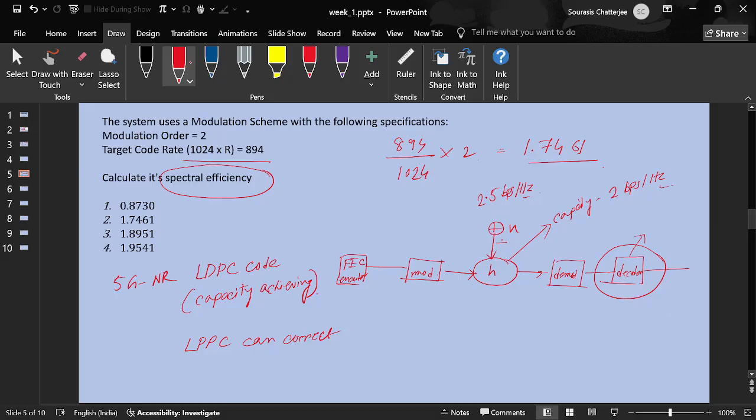I am not supposed to face any issue, right? Because I am using forward error correction, or I will encounter some issue. What do you think? Because if I am using error correction anyway, the decoder will work, right? I would like to know your thoughts about that. For example, my channel capacity is 2 bps, but I decide to transmit at a rate of 2.5, and my argument is that I am using LDPC coding. So I have this encoder block and decoder block, so it should be able to correct any error, right, or not?